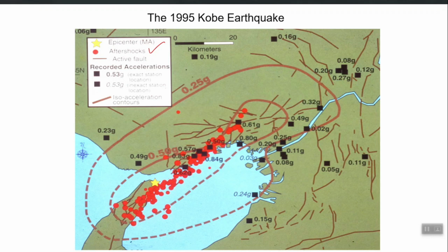In general they reduce, but sometimes you may see that at a particular site closer to the fault line the number is lower, and when you go away the number can be higher. It all depends on the local soil effect, because the recording station is situated on the surface, or maybe 2 or 3 or 10 meters from the surface, right? So the shaking can be modified by the top soil layer. Your station is resting on that top soil layer. Depending upon the soil type, the shaking can be modified by that soil, right?